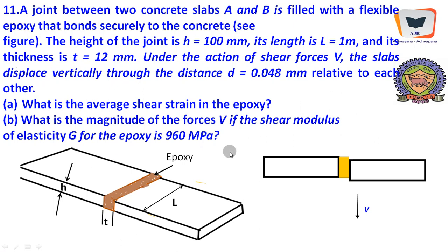We recall Hooke's law is applicable even for shear stress and shear strain. Under elastic limits, shear stress is proportional to shear strain, or shear stress varies linearly with shear strain, which brings in another measure of rigidity called the modulus of rigidity, which within elastic limits is related to shear.